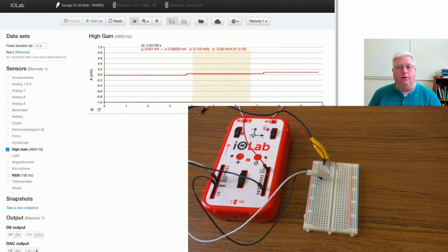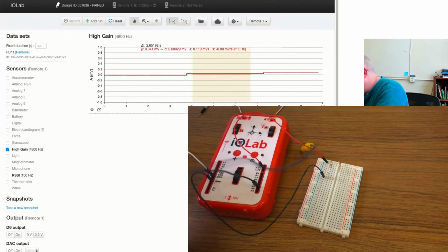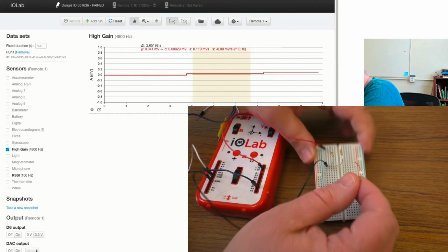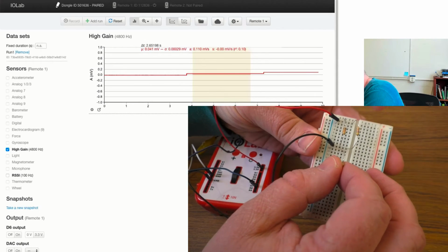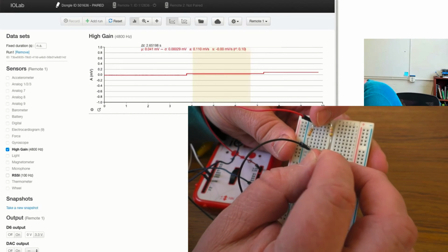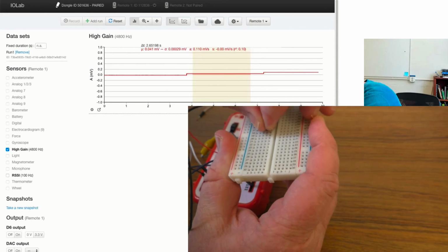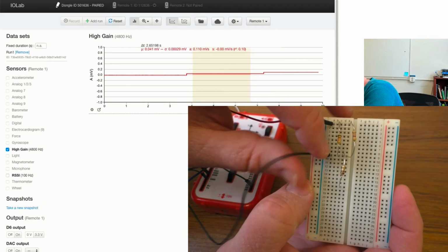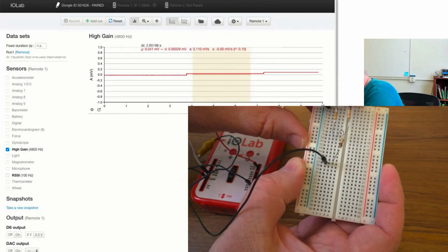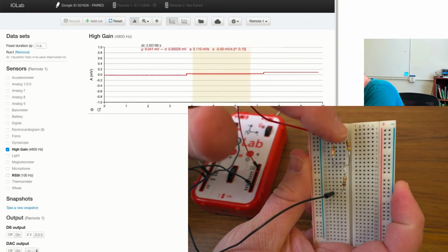So to do that, we're going to bring our 1 ohm resistor back so it can act as our ammeter to measure current. And so what I'll do to measure the current through the whole circuit is place the 1 ohm resistor in row 9 and 17. Okay, and now our circuit ends over here, so I'm going to move the ground over to row 17 as well.